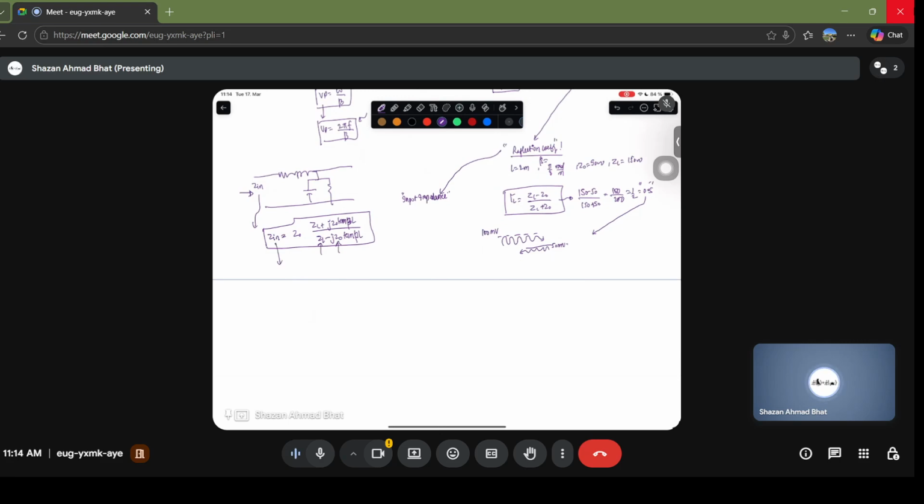You can obtain this input impedance and you get it approximately 30 minus 40j, which is basically complex. So it's complex. Obviously, we're talking about the reactances also, not only the resistances. This is the resistance part, this is the reactance part. So there are two: there is an imaginary part and a real part in this particular system.